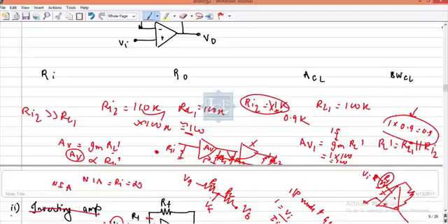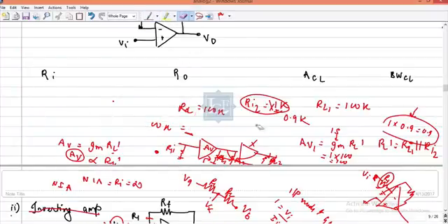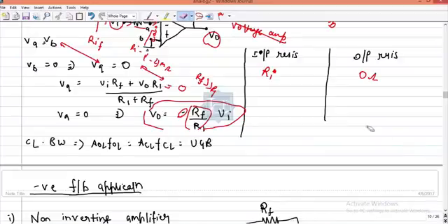What I know is this much only: the decrease in the voltage gain of the amplifier due to the low input impedance of the second amplifier is called loading effect. Now how can you overcome loading effect? If the input resistance of the amplifier is high, so we are saying that input resistance of the amplifier should always be high. Now this is an issue over here.